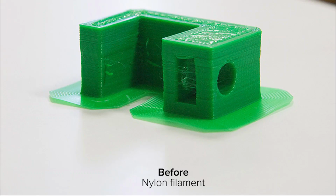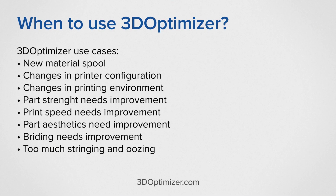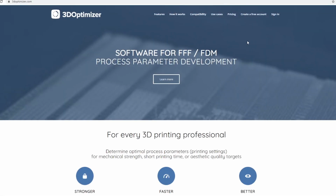3DOptimizer could be used when you, for example, purchase a new spool of material and don't know quite yet at what temperature your printer will print it best, what is the best retraction distance, and how well it will bridge. The way 3DOptimizer works is that it generates test G-codes, provides some guidance for test value selection, validation, and testing order. To start using Optimizer, you will need to create an account, but since I have already done that, I will proceed to log in.